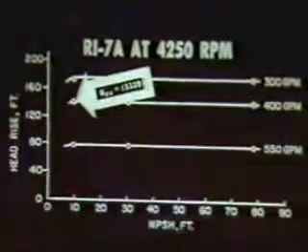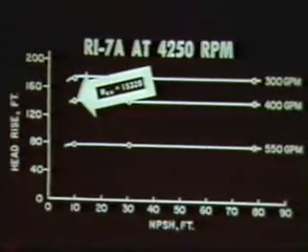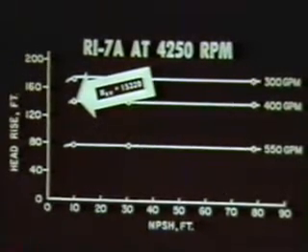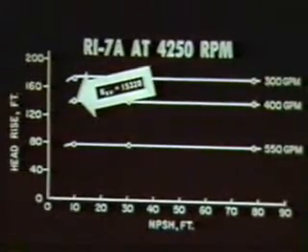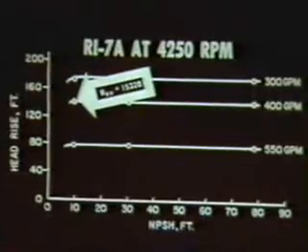The effect of higher positive flow incidence is evidenced by the increased depth of the cavitation bubble and tip vortex. Initial stalling of the impeller is characterized by the forward-swept cavitation cloud.